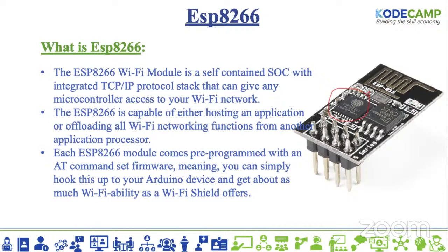Going further, when we start talking about the architecture and pinout of this particular microcontroller, we're going to see that not all GPIO pins are good for input. Some are good for output only. Though they are called GPIO pins, this matters a lot when it comes to the ESP8266. I'm talking about the NodeMCU version of this.